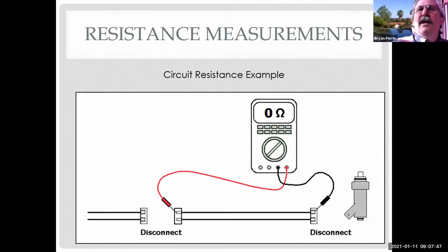Thank you. Right, and you hear me talk about high-level tests in this class. Using an amp clamp can be a high-level test. And one reason why we call it a high-level test is because it's quick to perform, and it quickly tells you, is there a problem here or not a problem here? But it doesn't tell you specifically what the problem is without more testing. But high-level tests have their place because they allow me to prove something's not the problem very quickly, as opposed to going in and doing all these other tests.